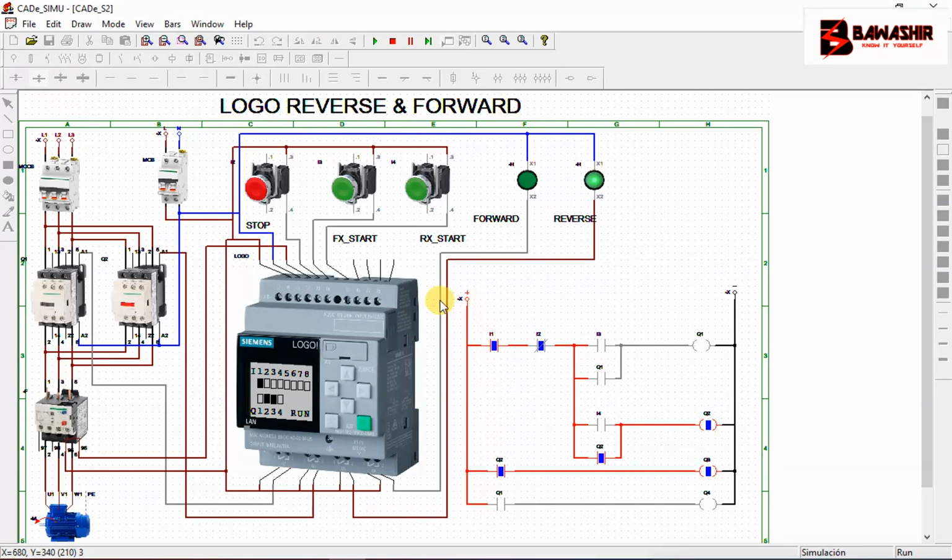Actually here the physical wiring, that's how we do it. But this ladder logic circuit we use programming software such as TIA Portal. Then we feed them in our PLC in case when we have any. Then the power line remains like that. We feed our gadgets like that, and everything is neat.